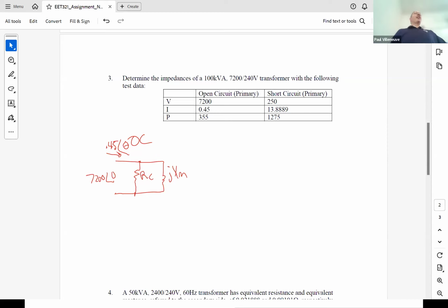All right. So how do we get theta? Well, remember the definition of theta is the angle of R. And if you remember, S equals V I conjugate is going to give us V I magnitudes, and the angle is theta V minus theta I. Is there any other angle that has theta V minus theta I in it? How about Z?